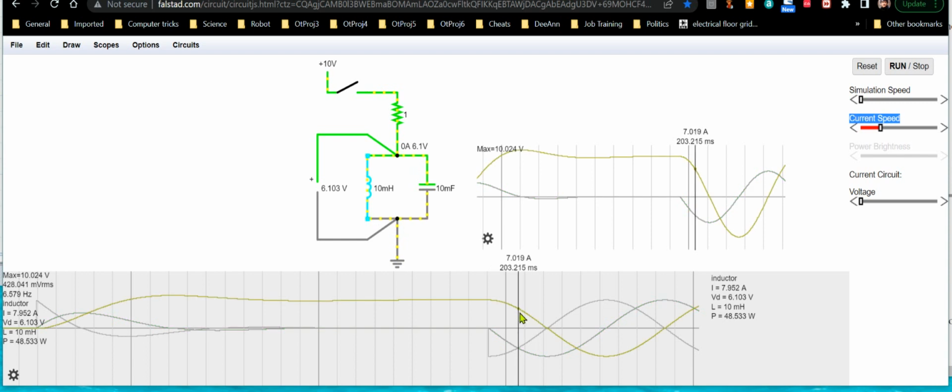It has to generate an infinitesimally higher voltage across the capacitor than the capacitor would naturally be at. So the capacitor is charging up because it's eating current from the inductor, and the inductor is slowly losing energy, but even down to the last little microjoule of energy it has in it, it is generating a higher voltage than the capacitor itself has on it.